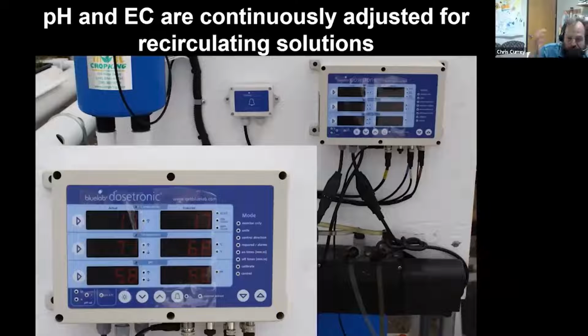If our nutrient solution is below our target EC, then a pneumatic pump will inject concentrated fertilizer or stock solution into our nutrient solution to raise the electrical conductivity until we see that target set point.